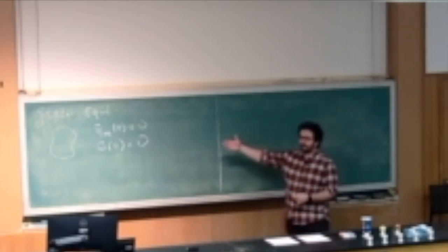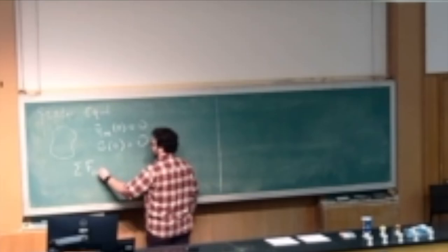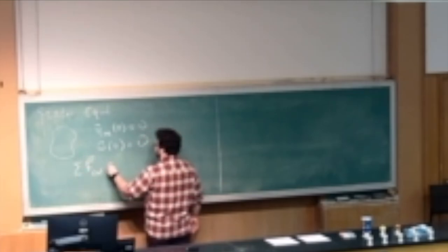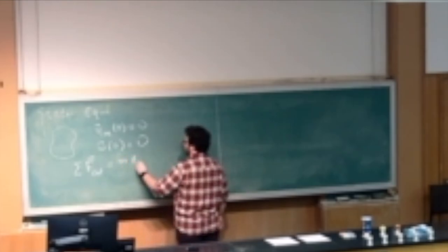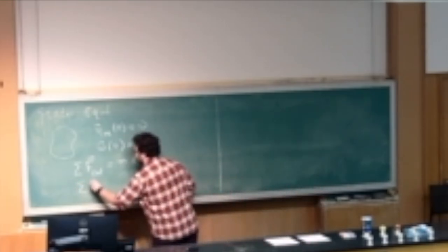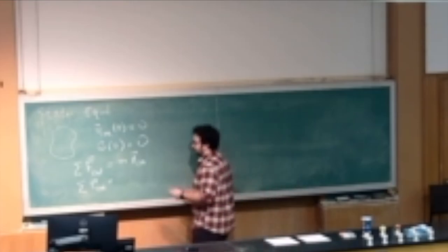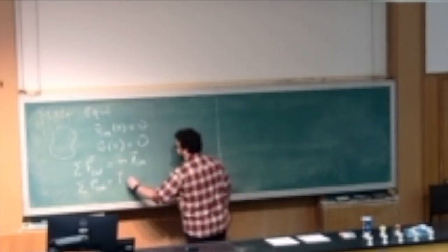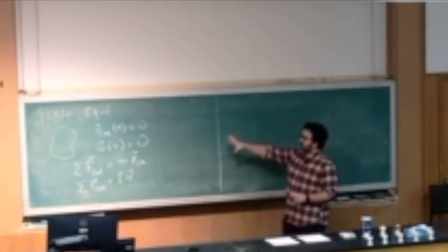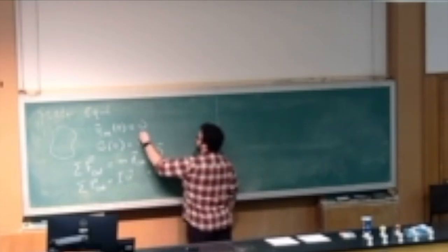Okay, now for the time evolution, for the later state of this potato, we are going to write down the Newton equation of motion for the external forces as well as the torques. So we have the sum of all the external forces equal to mass times the acceleration of the center of mass, and the sum of all the external torques, or moments as we like to call them in the business, should be equal to the moment of inertia times the angular acceleration. For static equilibrium, we are going to assume that the left-hand sides are equal to 0. And of course, to be more precise, these are all vector zeros.